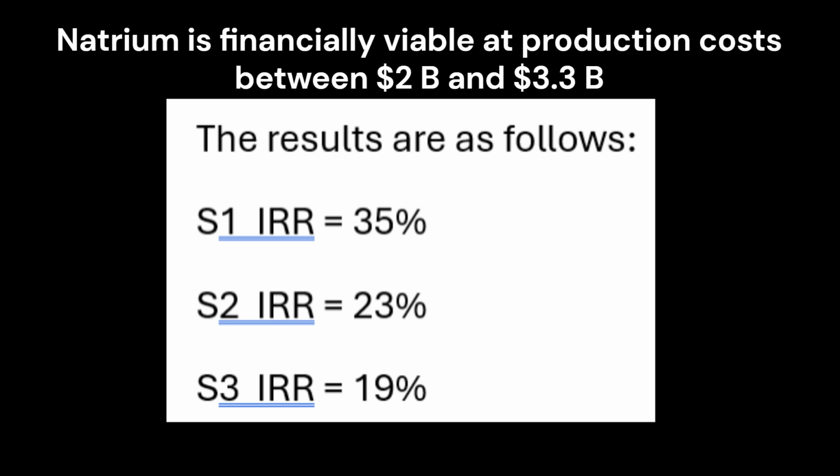A cursory examination would indicate the DTSR values are likely to be the limiting factor rather than IRR on decisions at the company level to proceed. Given the high capital cost, length of operation, and interest rate sensitivity along with government support expectations, these are general conclusions which may change. It is worth noting that the Natrium system was designed to complement renewables and not replace them. Its ability to use thermal storage is a key element that separates it from other direct competitors and provides that synergy. Given the history of nuclear plants, it is worth touching on items that might cause this IRR to be overly optimistic along with those working in its favor.